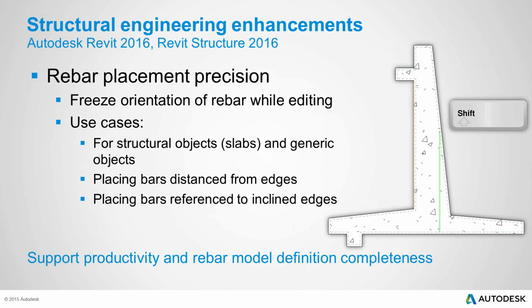Rebar placement position. So now you can see the big old shift button over there. We can hold Shift down as we're placing the rebar and lock the direction that the rebar is going as we're starting to sketch that in there. And again, this is available for, I believe, just sketching rebar. I could be wrong on that, but when you're going in there sketching that. So if you've got any battered walls in there, any of you Bureau of Reclamation guys out there, there are some great tools that were a lot harder to do before that now we can do a lot more nicely.